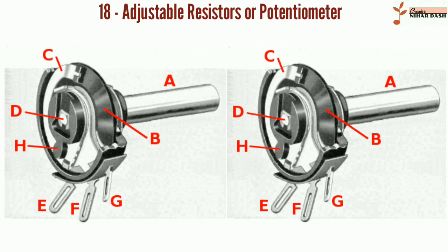An assortment of small through-hole potentiometers designed for mounting on printed circuit boards. A potentiometer, colloquially pot, is a three-terminal resistor with a continuously adjustable tapping point, controlled by rotation of a shaft or knob, or by a linear slider. The name potentiometer comes from its function as an adjustable voltage divider to provide a variable potential at the terminal connected to the tapping point. Volume control in an audio device is a common application of a potentiometer.